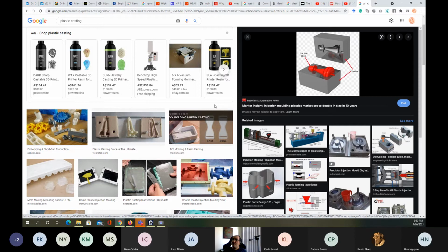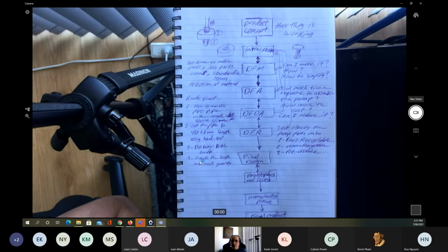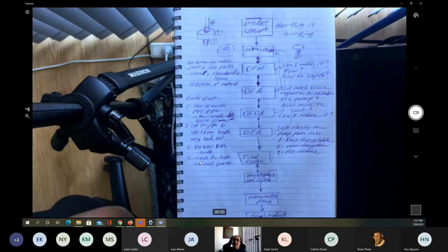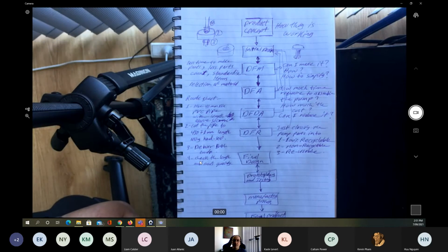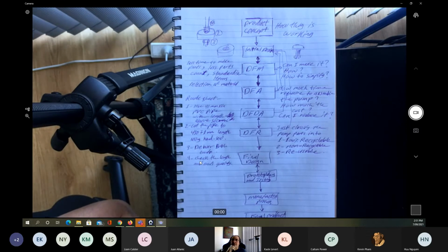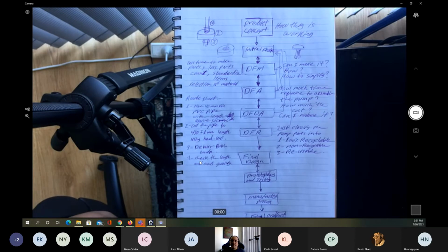Let's talk about another part. Of course, for the shaft, the process is going to be the same. We bring a rod with a minimum, let's say, 600 millimeter length, and then we start to cut it to 500 millimeter length, plus minus 2, and once again, file the ends. So we're going to get rid of the sharp edges, and then we're going to do the thread operation on both ends. This is another example of the route sheet.